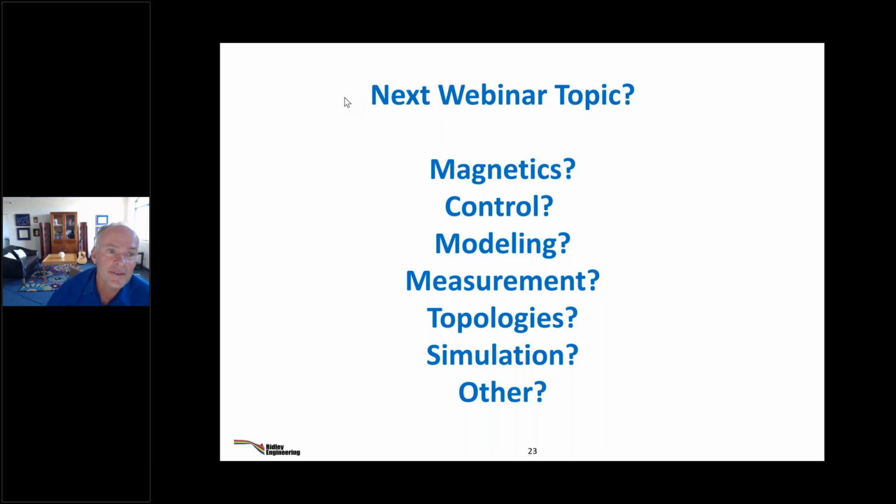Now it's 20%, sometimes it's 30%. But we are seeing buck converters now with 200% ripple on the output, and they turn out denser than anything else. So you've got this huge variation range in the buck converter that you don't have in an LLC. LLC looks like it's a really difficult converter and more opportunities to change things, but actually you don't. You're very constrained. Buck converter is wide open for design. So that's kind of cool about it.